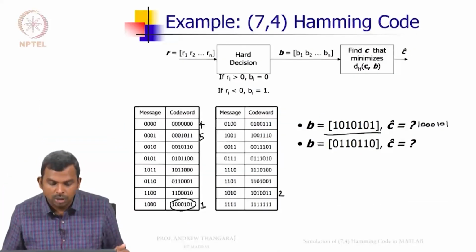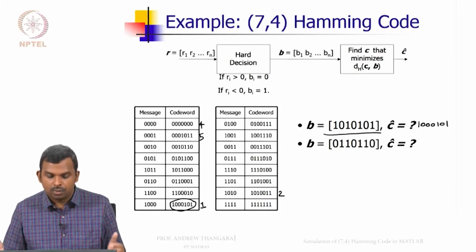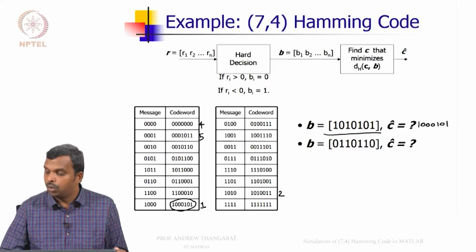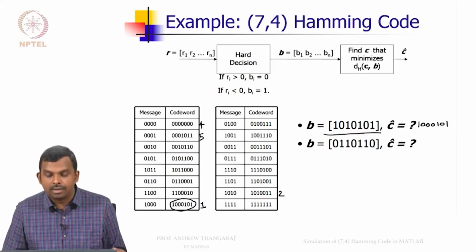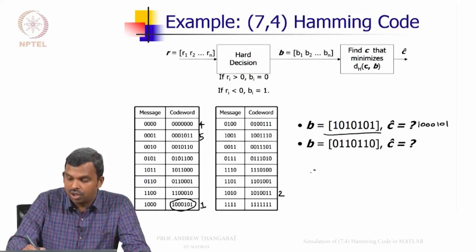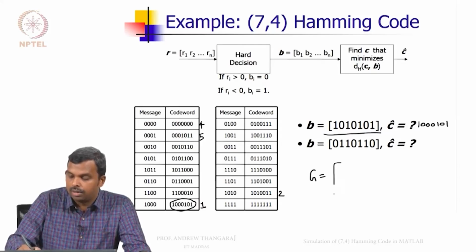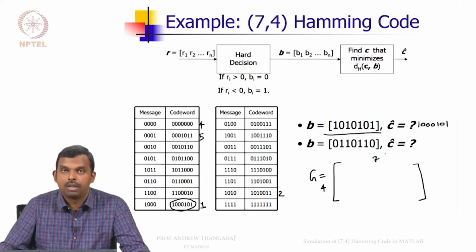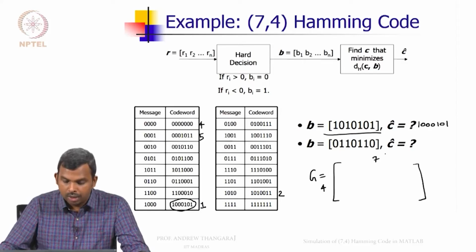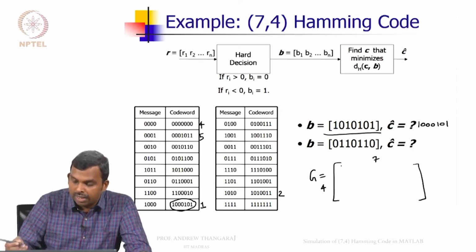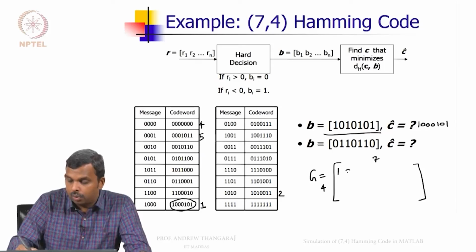So this is the Hamming code, the 7,4 Hamming code. I mentioned that this is a linear code as well, and one can write down the generator matrix for this linear code. So this would come out like this. So you have G equals, remember it is a 7,4 code, so it will be a 4 by 7 generator matrix. Okay. So it turns out since this encoding is systematic, you can quickly write down the generator matrix. So the generator matrix will look like this: